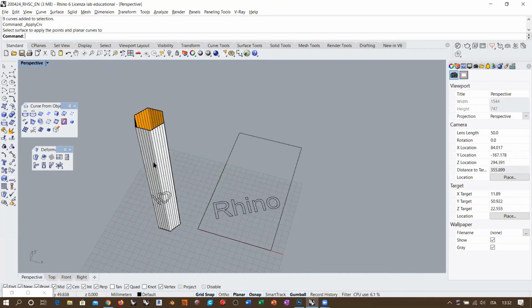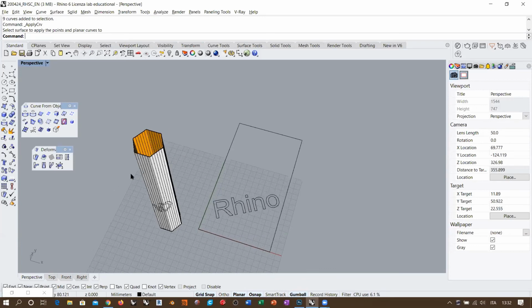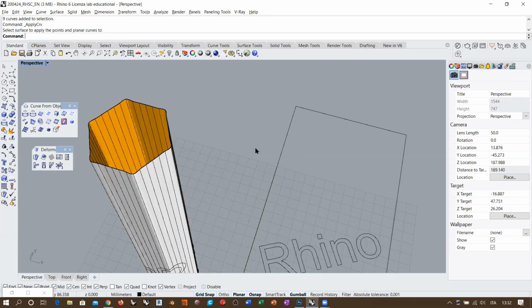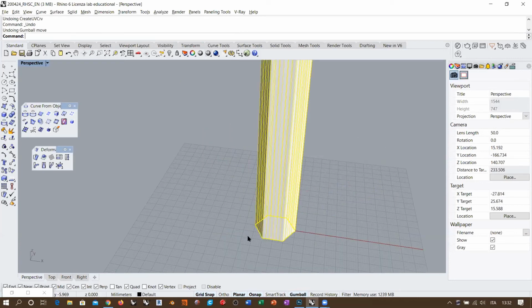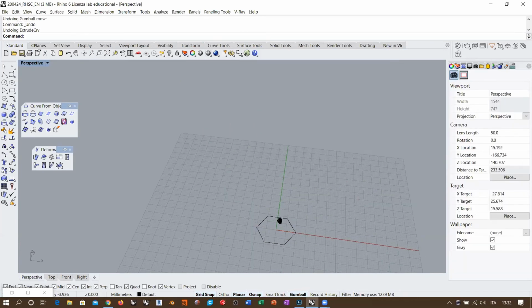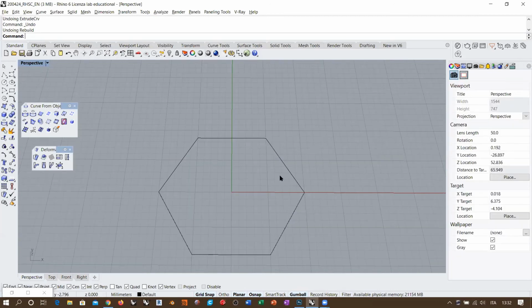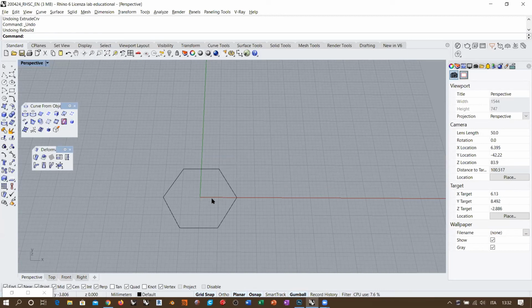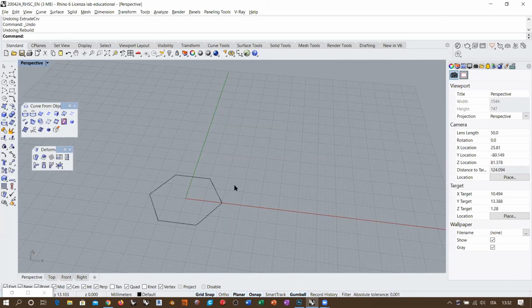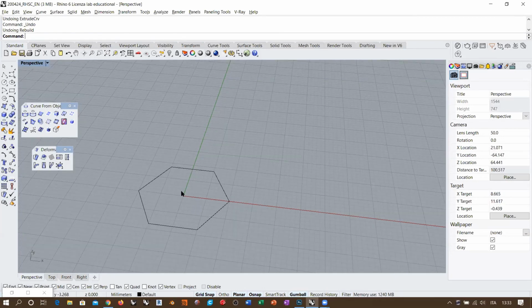But this is something that is actually changing, altering the topology, the shape of this surface. If I want to be more precise with the hexagonal shape, I would go back to this, and instead of rebuilding this thing, I would simply create smooth connection between the two edges in order to have an extrusion which looks a little more hexagonal, okay? Just with some rounding, but smooth rounding along the edges, okay?